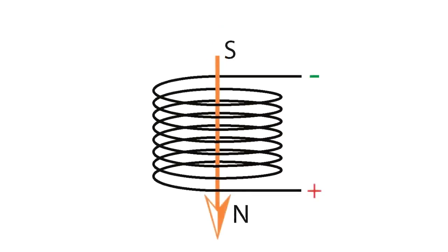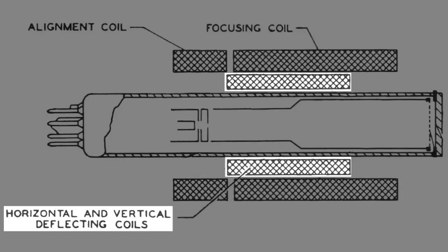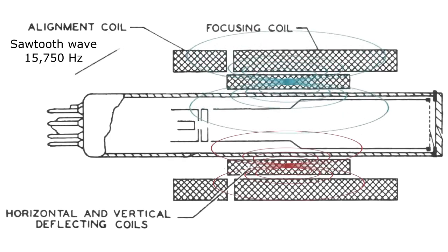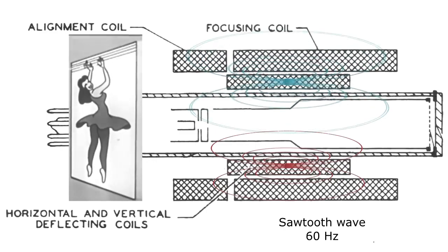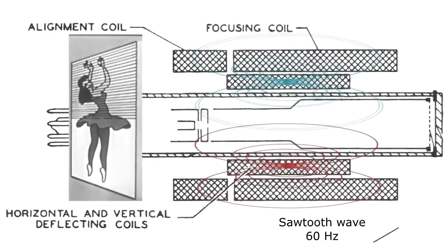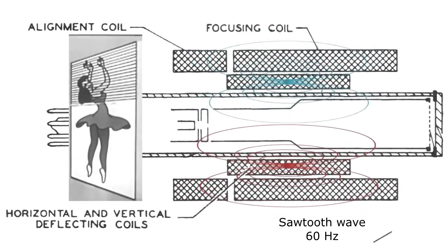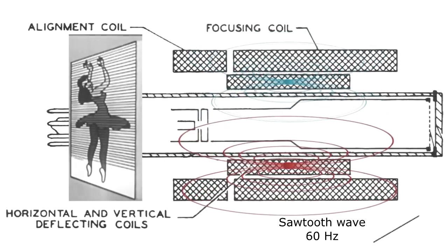In summary, 4 lines are blanked at the base and 12 lines at the top in each field. In the total frame of the two fields, 8 lines are blanked at the base and 24 lines at the top. The scanning lines produced during vertical retrace, but which are made black by vertical blanking, form black bars at the top and bottom of the image. The image height decreases slightly with blanking, compared to an unblanked raster. However, the height can be easily restored by increasing the amplitude of the sawtooth waveform for vertical scanning.